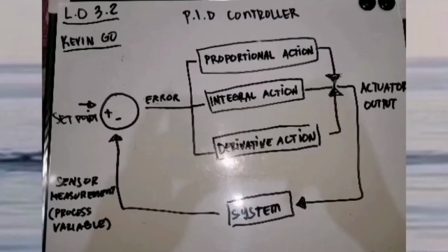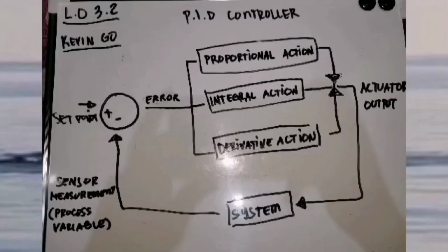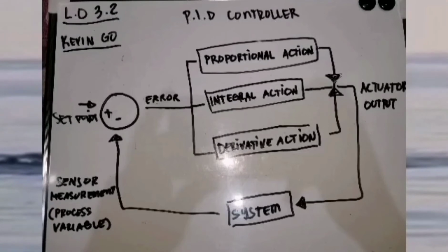The PID stands for Proportional Integral Derivative control. As its name implies, a PID controller combines a proportional control with additional integral and derivative adjustments, which help the unit automatically compensate for changes in the system. So basically, the PID controller's job is to measure process conditions, calculate feedback, and adjust output to force the process level to match a set point.